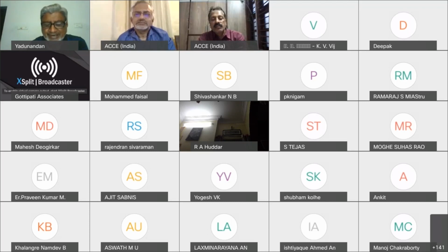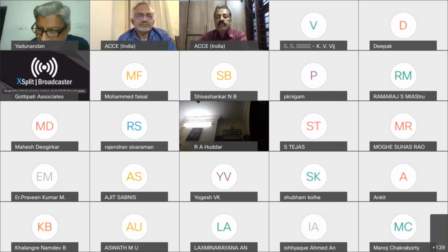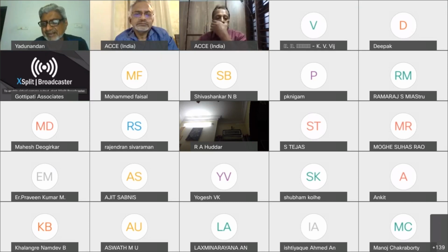Yes, you can do that, provided you take care of the beam column junction. One thing, in the reinforcement calculation at the beam column junction for the negative moment that is coming there, you consider the column strength, the concrete strength, and do it carefully. That's all, for the negative moment only. Negative moment at the outer supports wherever columns are coming, because it's a big hall, with the end moments. I think it will certainly be possible.